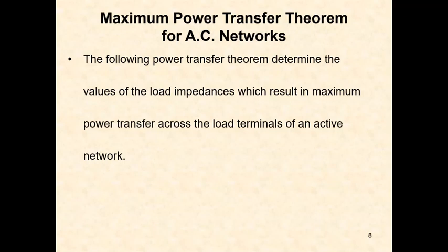Now I am going to discuss the AC circuit. Practically, DC circuits are generally not there; AC circuits will be there. In communications, everything is at higher frequencies, which is AC only. So now I am going to discuss the maximum power transfer theorem in AC circuits. The power transfer theorem determines the values of load impedance which result in maximum power transfer across the load terminals of an active network.